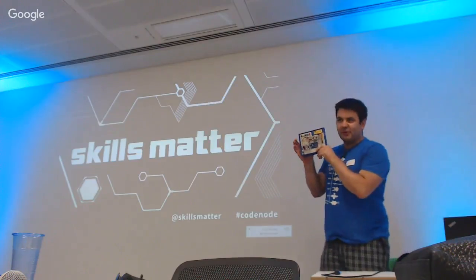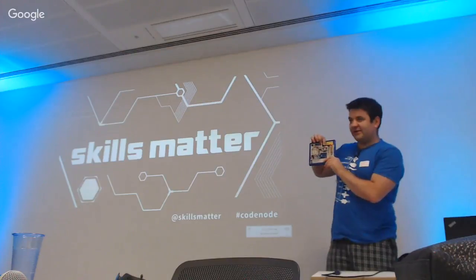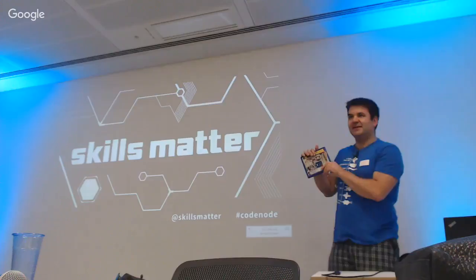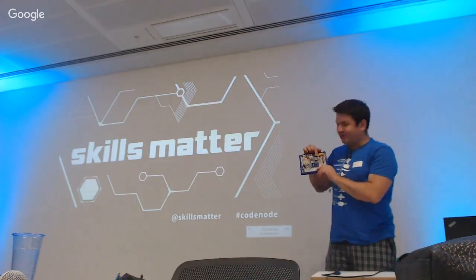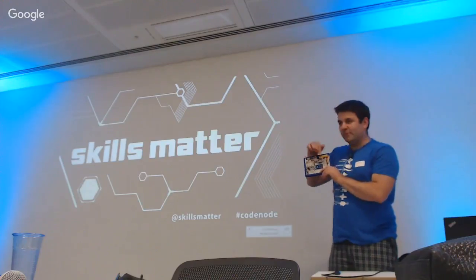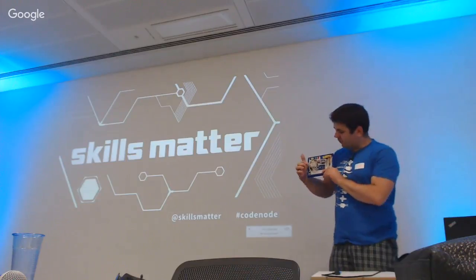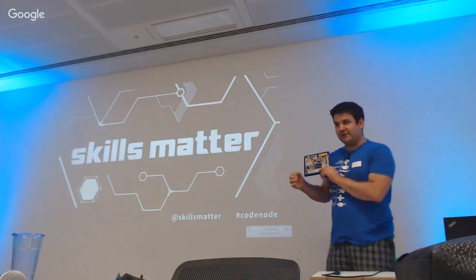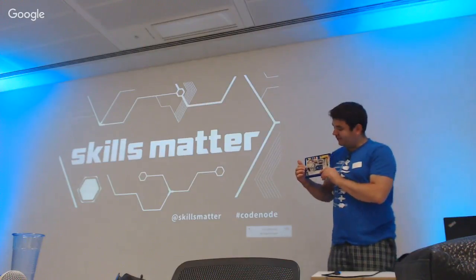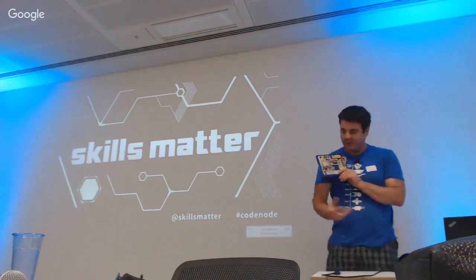So this is a prototype board. At the heart of it for Wi-Fi is an ESP8266. That's the one, and that does all the Wi-Fi comms. The problem with these is that they're reasonably high power drain compared to other things. So I've got a PIC chip, and the PIC chip can run on almost no power at all when it goes to sleep. So the idea is that the PIC chip runs the orb.